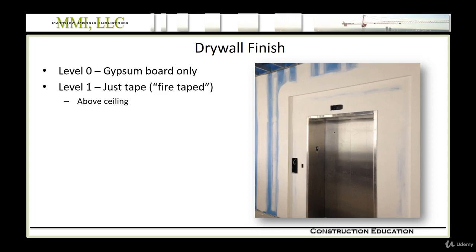Another option is called a bazooka, and it kind of looks like it sounds. The concept's pretty similar to a banjo. A bazooka has a long tube full of joint compound, and also a roll of tape on that long tube. And it's nice for reaching elevated locations, and it's also very fast. And every finisher has their preference for what they use, but either way, it's much quicker than doing this all by hand.